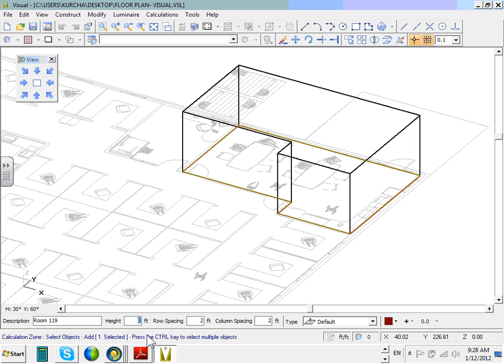Right next to it, the height. Guys, height. All the offices and lunchroom, they do the calculation at 2.5 feet. Hallways, we're going to do the calculation at 0. Okay, I will write these for you. All the offices, lunchroom, we're going to do the calculation at 2.5. So what do you think I'm going to put here? When you do calculation, guys, you have 2 options. Option number 1, 0, that will do the calculation right where your foot is located here, Chris, on the floor.